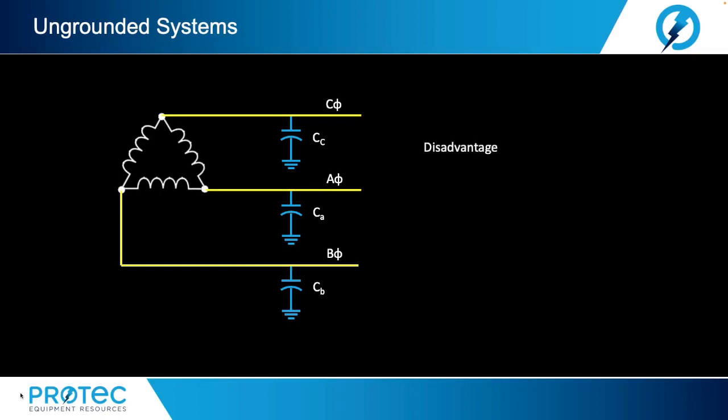Now, unfortunately, this type of system also offers some big disadvantages. One major disadvantage to the ungrounded system is difficulty to locate line-to-ground faults. Finding the fault is a time-consuming process. For that reason, it's often done on weekends so that a company doesn't have to shut down its normal production processes. In addition, the fault must be located and repaired relatively quickly because if a second fault occurs, the fault acts like a phase-to-phase fault, extending the repair process.